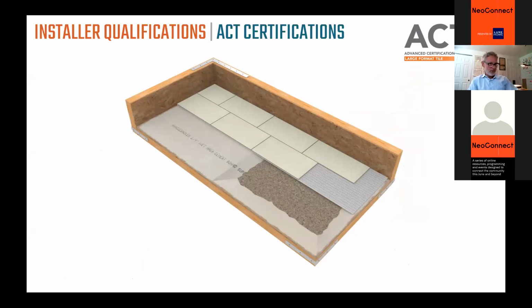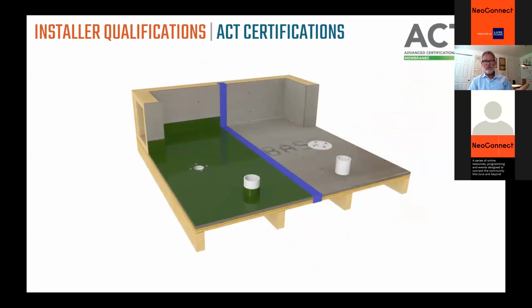So here's the thumbnail for large format. The installers are tested on their ability to evaluate and flatten the floor, to install the tile with good grout joints with minimal lippage. We look for that 1/3 offset. We look for 95% coverage, and we look for a good finish.